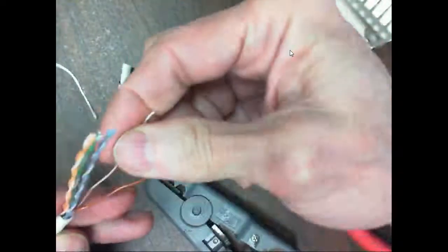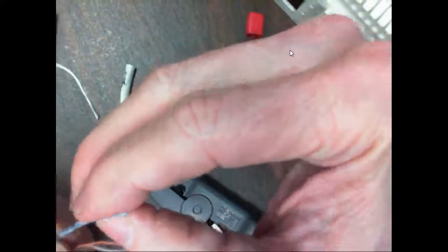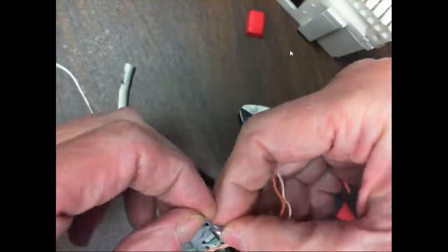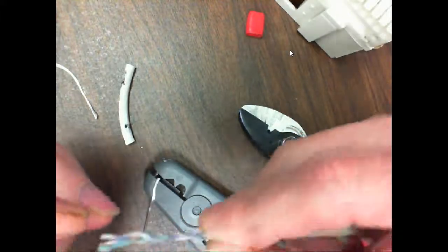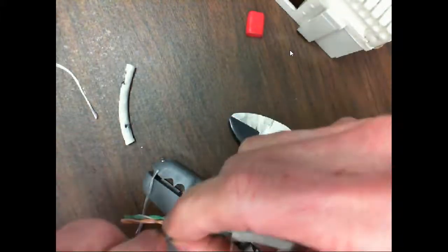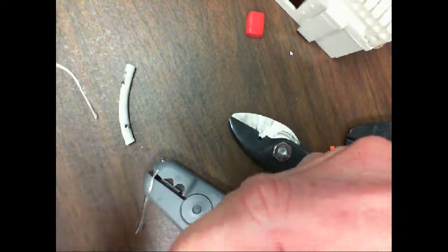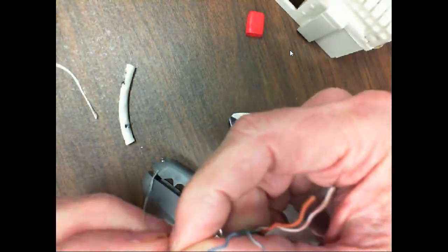And then I'll come up here and I'm going to take these guys and untwist them. I'm going to untwist them all the way back to the jacket. And then I'm going to take my crimp tool or something that's got a rubber handle on it, and once I get them all untwisted, I'm going to use that to get the twist out. Okay, you understand? So we strip off enough so we can manage this thing and untwist these. If I strip it down here, it's going to be hard to get the twist out of the section that's supposed to go into the individual little slots. So I can come up here and just untwist these.